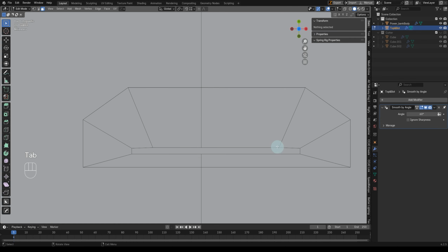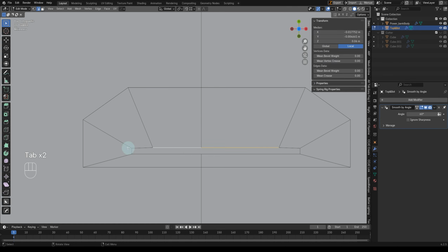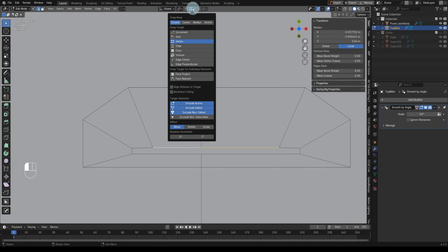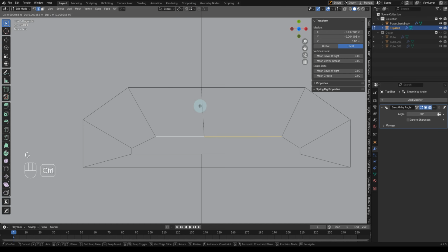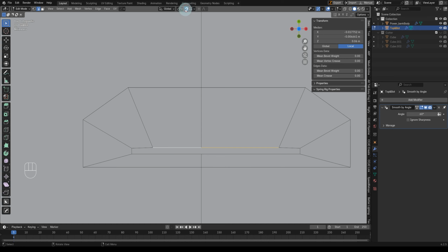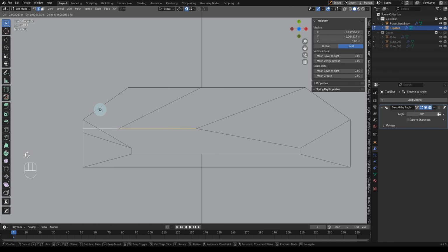Okay. I want to snap it. Okay, cool. So then this edge too, I want to snap it to this place. Remember I changed my snapping to vertex. If you click on this icon, what I've been doing since was that this icon was not on, but when I move, I hold down Control and then I hover my mouse to where I want it to be snapped to, okay? And it snaps to that particular point. But in this case, if you enable the magnet, the snapping icon, now you press G, the moment you move to any point, it snaps to that point, okay? But now I want to constrain it to the Y axis. So I press Y, so I have a constraint to the Y and then I'll move my mouse here.